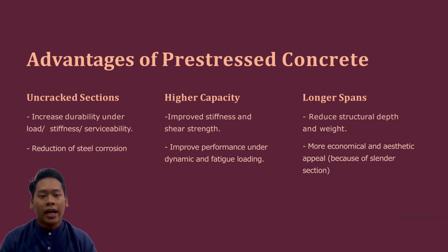And then, higher capacity. Pre-stressed concrete offers improved stiffness and shear strength, allowing it to bear greater loads. For the last one, longer spans. It enables longer spans by reducing structural depth and weight, making the structure lighter and more efficient. Thus, it will make our structure more aesthetic and require less cost during construction.